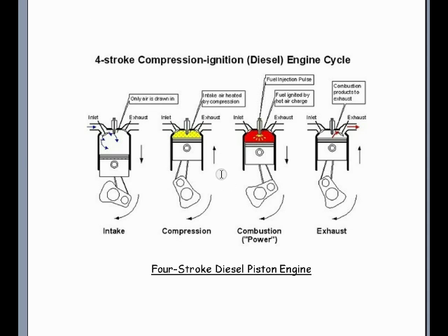You have to remember that on high compression heat of air compression engines, such as diesel and turbine engines, a slow burning, hard to ignite fuel must be used. Gasoline is so volatile that it instantly goes from liquid to gas in open air due to its high volatility. But kerosene jet fuel and diesel fuel are very similar in the sense that they are not very volatile in open air, and in order for them to ignite, they require extreme amounts of heat of air compression to do so.